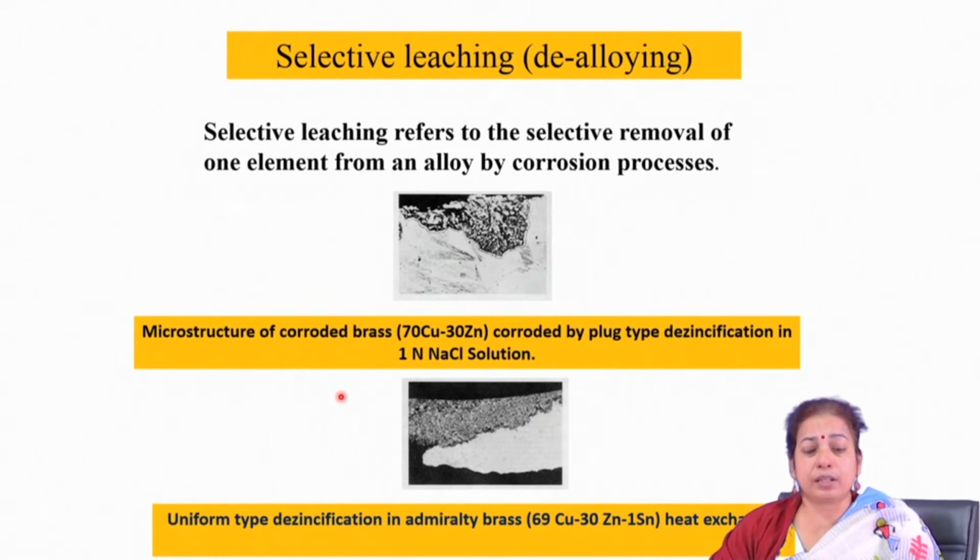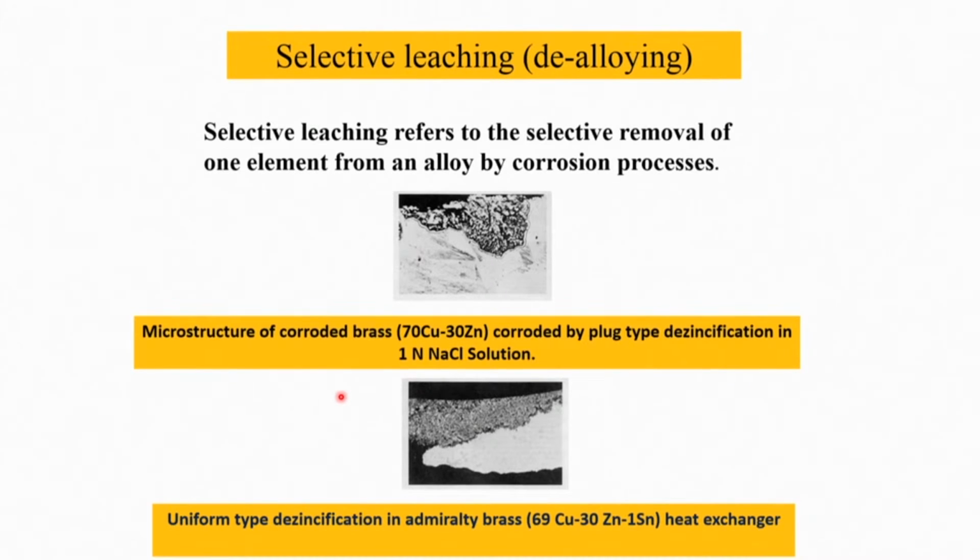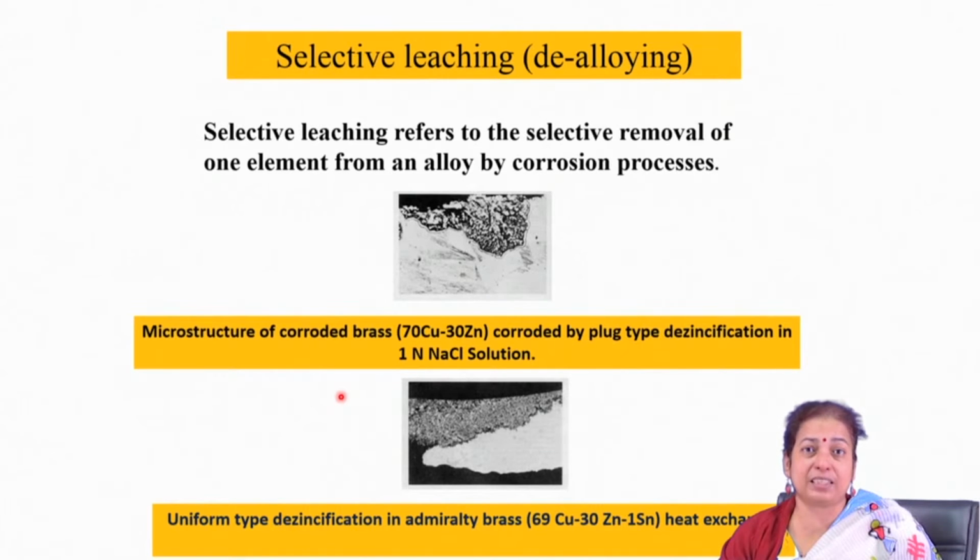So, we discussed the different ways to address these problems, but one of the important ways by which this problem can be solved is by solutionizing operation. If you talk about a surface treatment process which might be applied for the mitigation of intergranular corrosion, that may be surface melting, because otherwise it is very difficult to mitigate this kind of problem. It is done by the typical bulk heat treatment, or by addition of microalloying elements in the microstructure during alloy development.